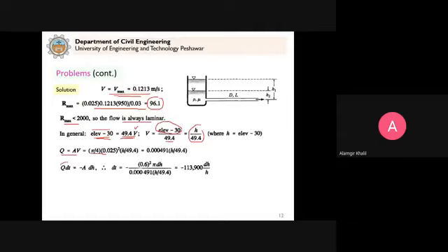Now we have this as the volume, Q into dt, the volume. Similarly, A into dH, this is also a volume, AS into dz. Remember, Qi is 0. Why minus? Because Qi is 0. So in this case, also the depth is decreasing with time, so the negative sign comes. So now from here, dt will be equal to minus A H dH divided by Q.